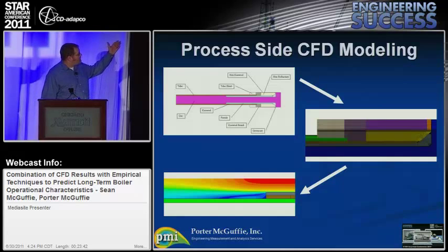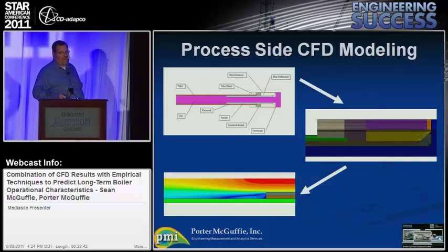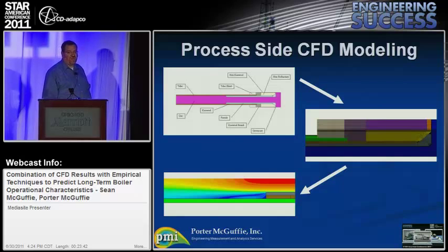We took this geometry, developed a CFD model that you can see in the middle right-hand side, and then analyzed that at several process conditions. The most important piece of data that we can get out of this analysis is what occurs just downstream of the ferrule. Obviously, there's a sharp geometric discontinuity that introduces swirling and turbulent flow, and actually introduces a significant peak heat flux that occurs just downstream of the ferrule, which also corresponds to your peak temperature.